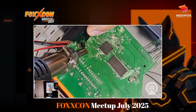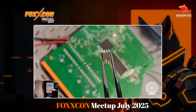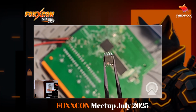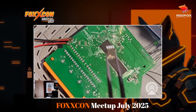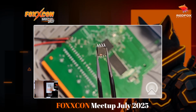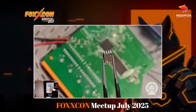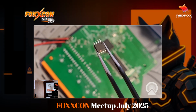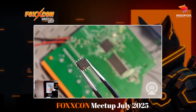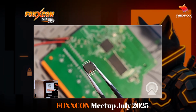Yep, and here we have it. Okay. So this is the NAND flash that we are going to inspect today. The specific reason why we took this out instead of any other thing is because this stores the entire operating system and all the binaries that we want to look at. Also, you would be able to see there's a dot in the upper left corner, right? That dot specifies where the pinout starts. So whenever they say first pin, the pin that is right beside that dot is where you start counting downwards.